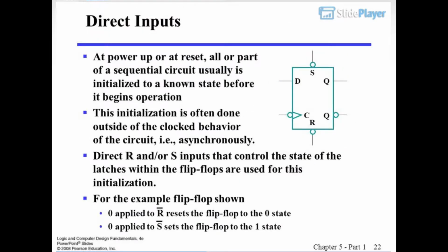Direct inputs. At power up or at reset, all or part of a sequential circuit usually is initialized to a known state before it begins operation. This initialization is often done outside of the clocked behavior of the circuit, that is, asynchronously. Direct R and/or S inputs that control the state of the latches within the flip-flops are used for this initialization. For the example flip-flop shown, 0 applied to R resets the flip-flop to the 0 state. 0 applied to S sets the flip-flop to the 1 state.